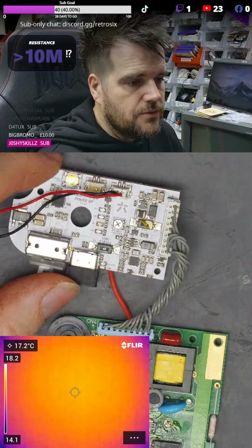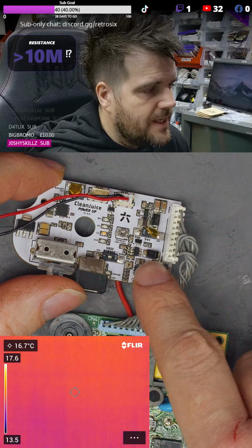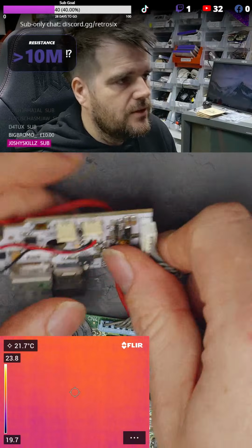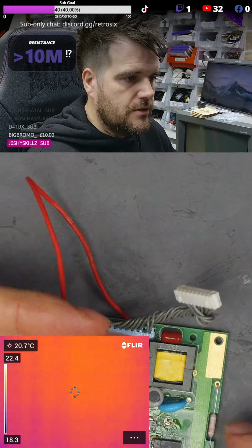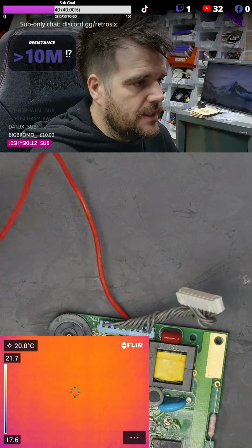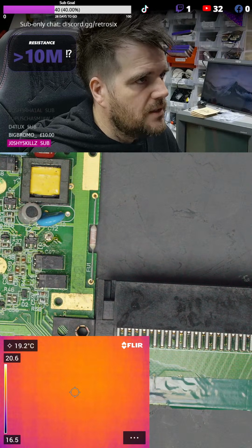So again, when you look for thermal, you have to bear in mind that it's not always just where the heat is. You have to think, right, the heat is coming off this board from the 5-volt rail. So you want to disconnect the 5-volt, send the power through the bench supply, so the bench won't get hot. Then you know you're not dealing with the power supply, and then you can track down. So you have to be aware of that as well.